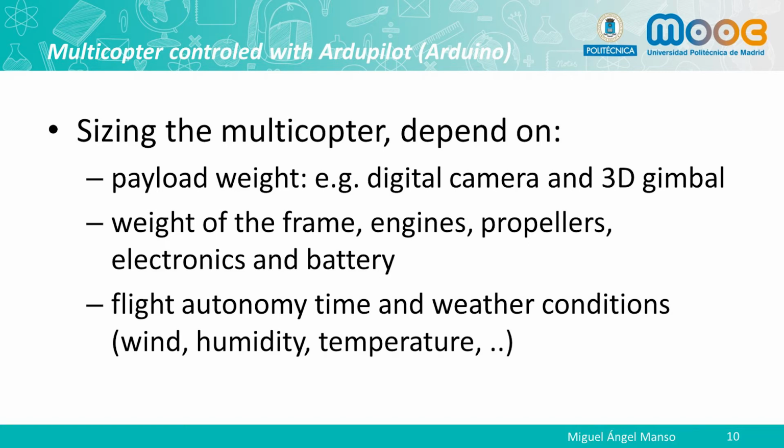To calculate the flight autonomy, the weight of the entire multicopter at takeoff, including payload, must be calculated. The characteristics of propeller and motor operating and consumption regime must be known to calculate the power consumed to support all the weight in stationary conditions.